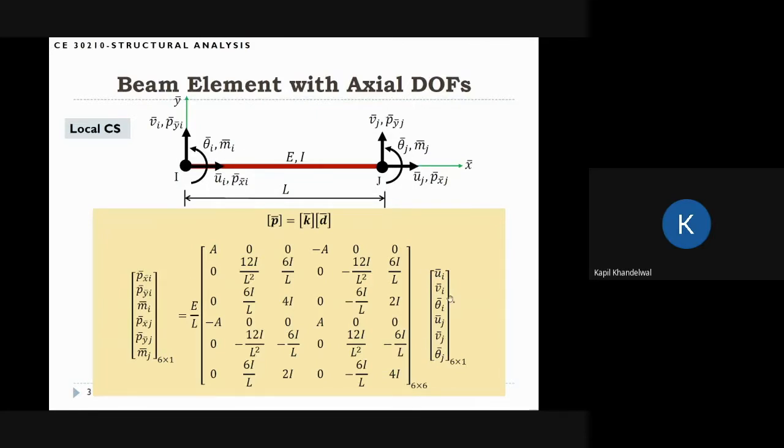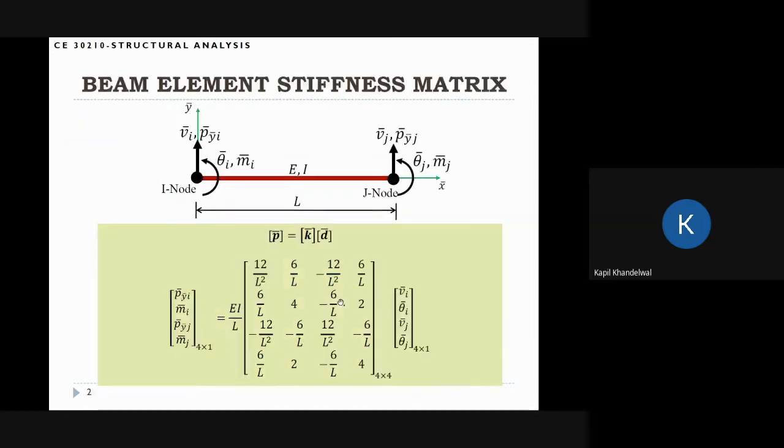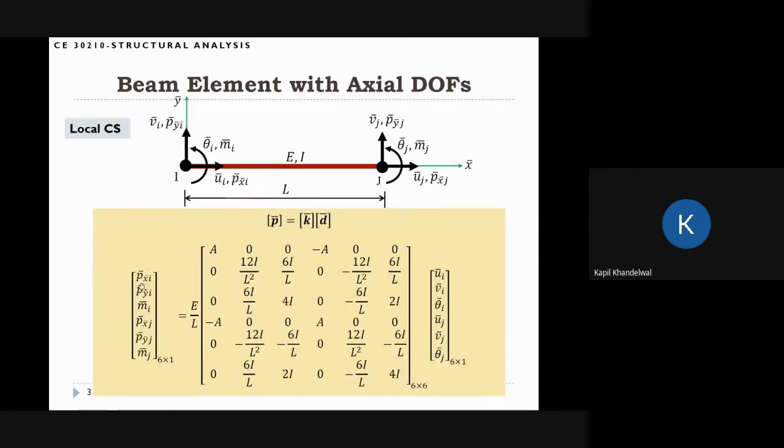And it turns out that for the stiffness matrix, what we have to do is just add the stiffness coefficients for the bar member, because in the axial direction, this member is just a bar member. Because axial and flexural effects are uncoupled, we can just take the bar member stiffness coefficients and add them to this matrix. So I have taken this stiffness matrix and expanded it to 6x6 size, and for Pxi and Pxj, I'm just putting in the bar element stiffness matrix. The stiffness coefficients I'm putting in are EA/L, minus EA/L, EA/L, minus EA/L.